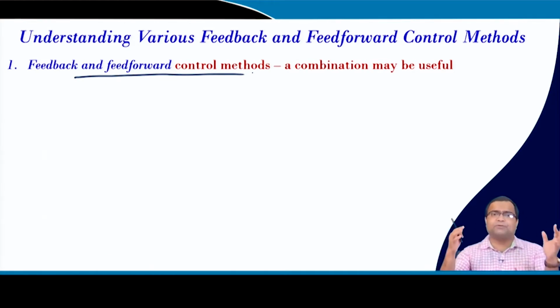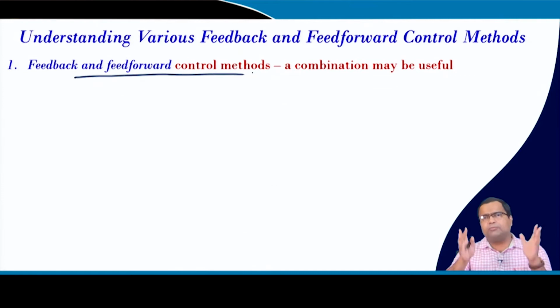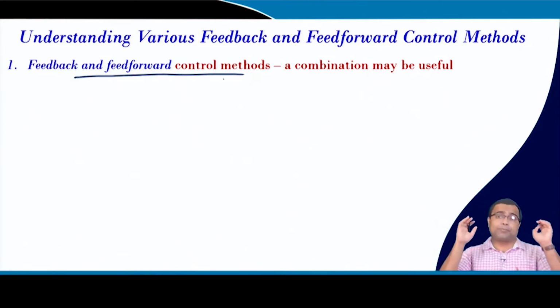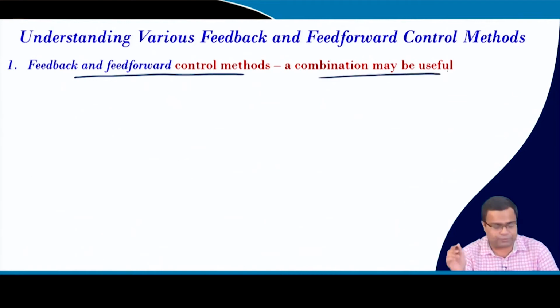because if you recall, voltage mode control suffers from poor line regulation, current mode control suffers from poor load regulation. So, for voltage mode control, we need to consider input voltage feed forward. For current mode control, we need to consider load current feed forward. By this feed forward method, we can make their performance very fast, and make them almost insensitive to the disturbance, with an excellent disturbance rejection property, and this can be very useful.